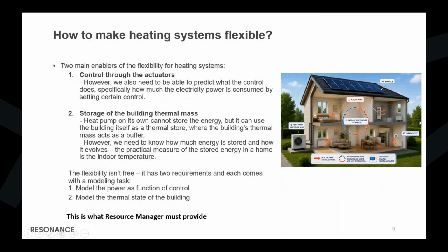So before we build anything and delve deeper into the modeling, let's first get the intuition on what it actually takes to make a heat pump or heating system flexible. There are 2 main enablers of the flexibility for the heating system. The first one is the control through the actuators. So we need to be able to control the heat pump. In practice, this is done remotely through the actuators such as the thermostat set points.